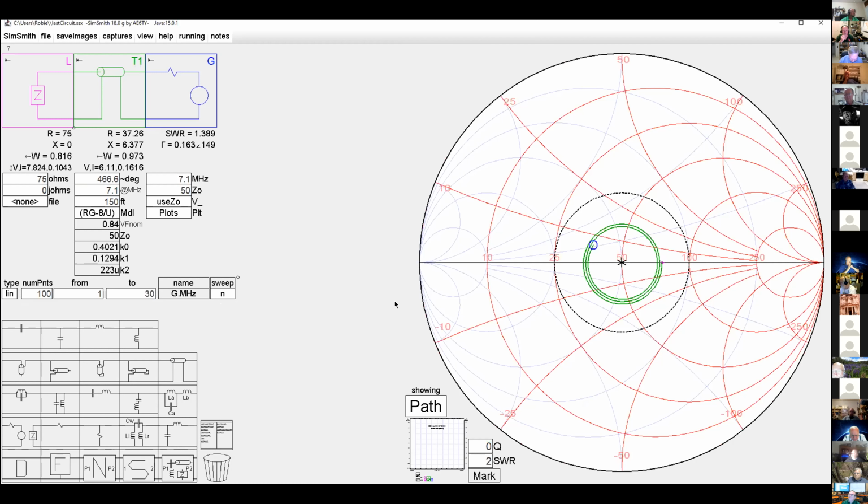So can you have a great impedance at the antenna, a great SWR at the antenna, and have a lousy SWR at the rig? Absolutely. Well, can it go the other way? If you have that, you probably have other problems in measuring your SWR, probably currents on your line. Probably external common mode currents flowing on your transmission line. They're fooling your instrument.